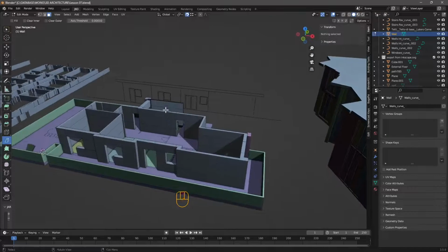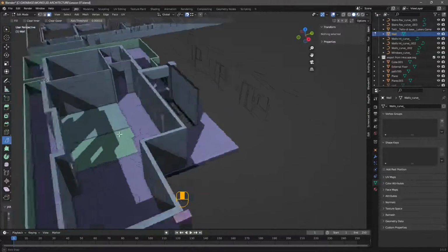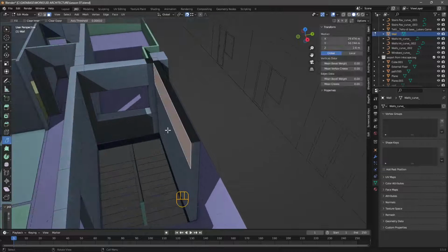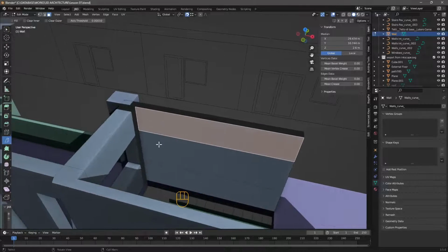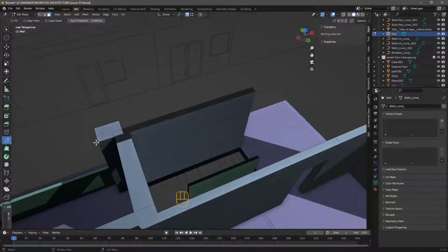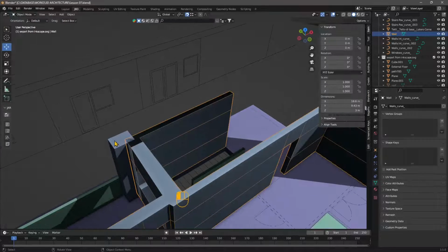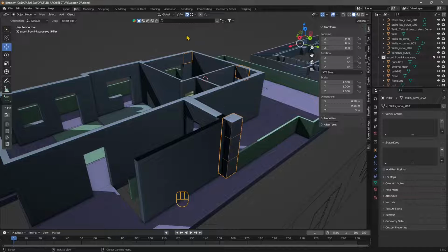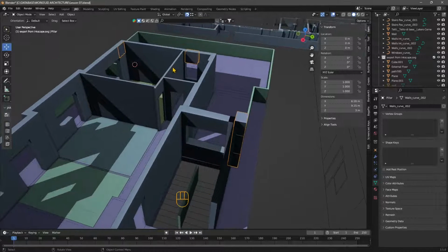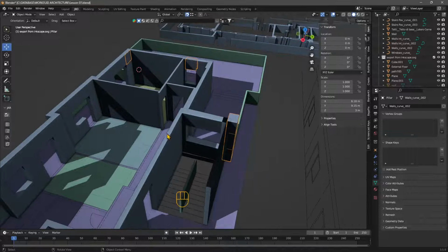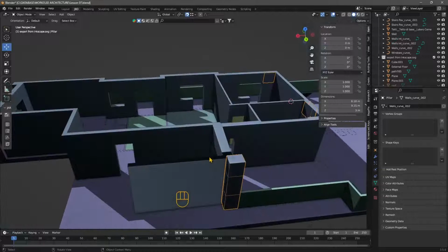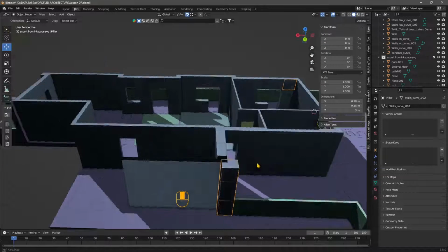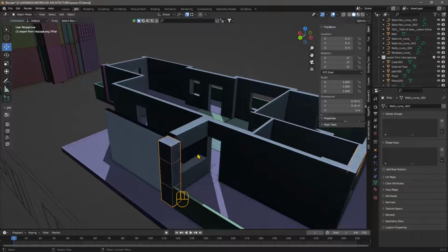We're going to do some fixing, some adjusting. So for example, right here, we have an issue. Now in the previous video, we separated the pillar right here. So we can create pillars with the extrusion just as well as external walls. In this video, I'm also going to show you how to create internal walls like this, and how to add cuts, and how to create voids using cuts, so how you can add windows and doors later.